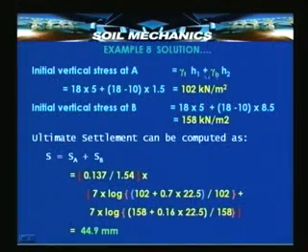Okay. Now, what is the vertical stress at A due to the overburden? Remember that there is a dry soil layer and a saturated soil layer. The water table is somewhere in the middle, and wherever the soil is saturated and below the water table, you have to take the buoyant unit weight. Therefore, the intensity of pressure at A due to the overburden will be gamma T into H1 for the dry part and gamma buoyant into H2 for the buoyant part, that is 102 kilonewtons per meter square. And similarly, at B you can calculate the intensity of stress due to overburden as 158 kilonewtons per meter square.